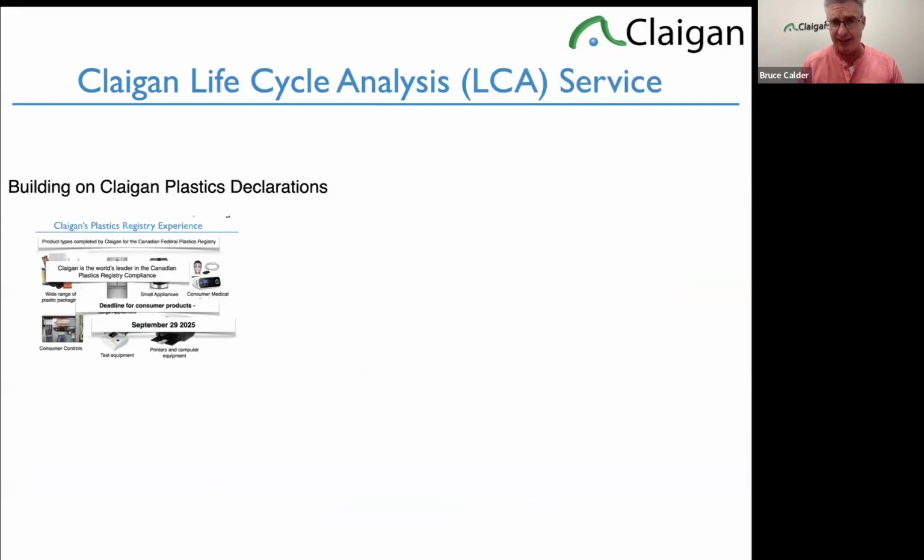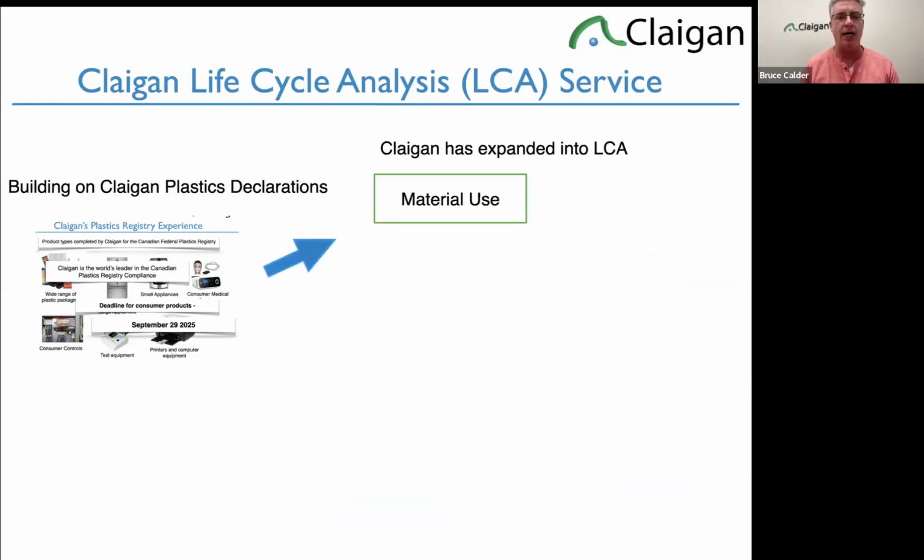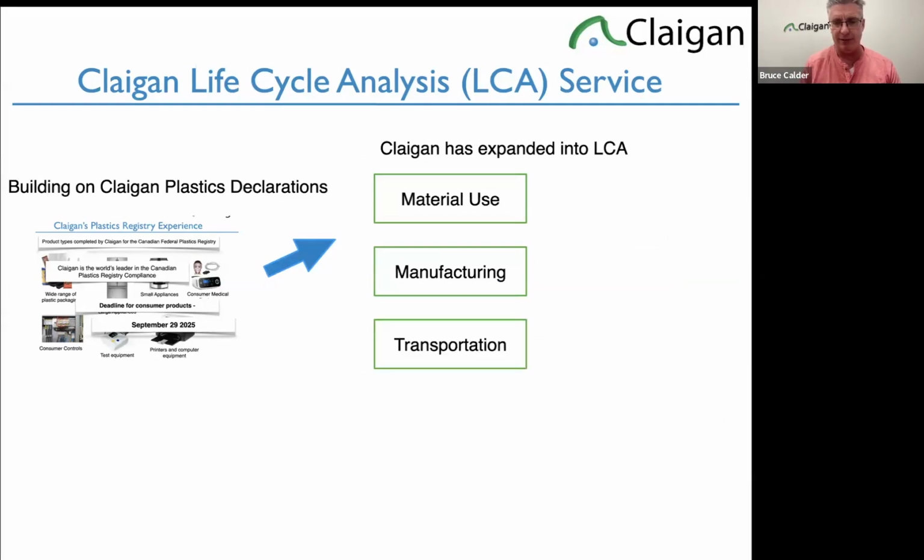We also do life cycle analysis. The plastic registry infrastructure has given us this tremendous infrastructure. The hardest part of LCA, which is the material side, that is the hardest bit because the manufacturing side isn't that hard. Transportation is fairly straightforward. How many kilometers of each transportation mode does it take to get to the customer? Usually the average customer in the EU. Product use, how much energy does it use during whatever your target window is? Target window, for example, could be for a printer, 100 printed pages, for, say, test equipment, 1 million tests, for a laptop, like a 5-year or 7-year life.